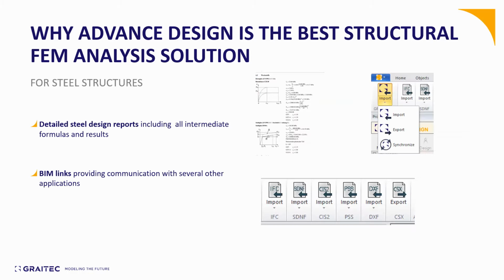After you have performed the structural design, one of the important parts is the reports. If you want to investigate what is wrong with a specific element, or if you want to create a report to send to an engineer, Advanced Design can provide you with very detailed steel reports that can also be modified. We also have templates for our reports, so you can define your own templates, and based on that template, the report will be generated. You have the option to modify it, remove items, add chapters, etc.